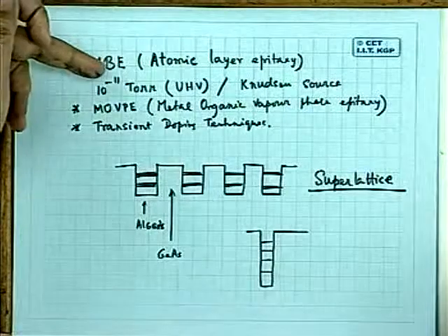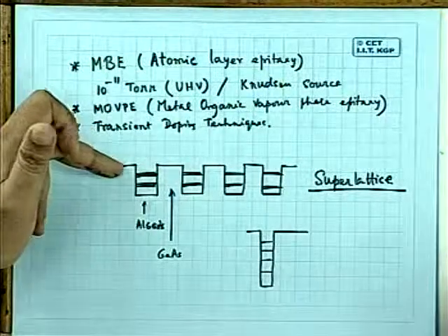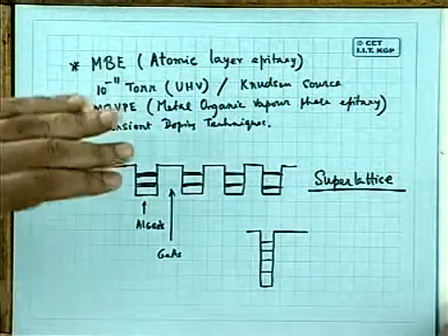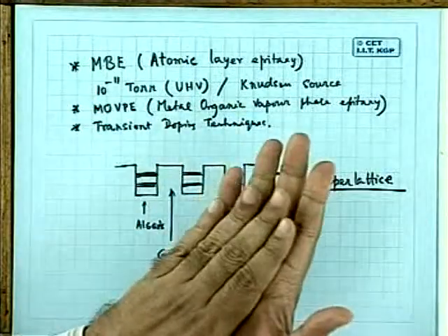It is sometimes also done by doping. By simply doping variations it is possible to do this, because with higher doping the conduction band comes closer to the Fermi level, same technique. But naturally you will not get that deep wells. If you want deep quantum wells, the only way is to use heterostructures, two different semiconductor materials with very good lattice matching. Otherwise you cannot successfully grow the layers.